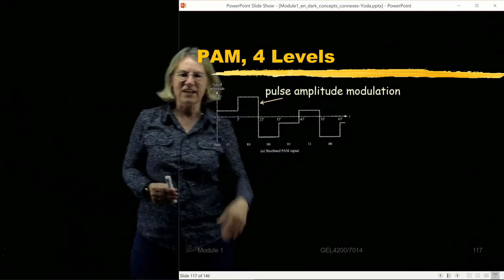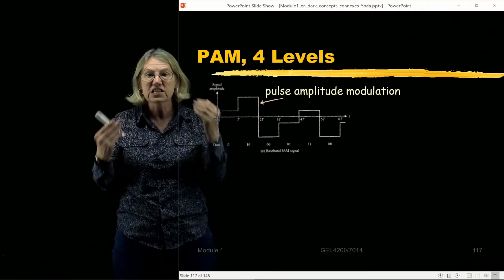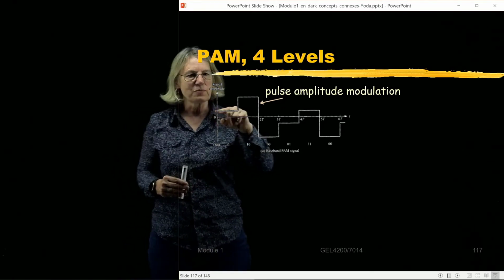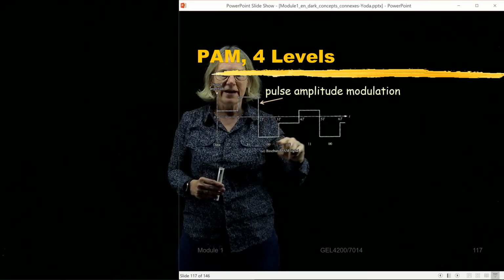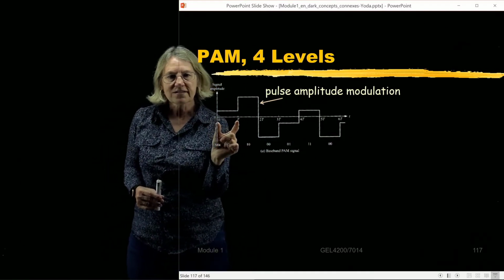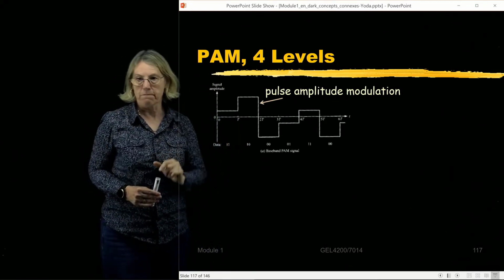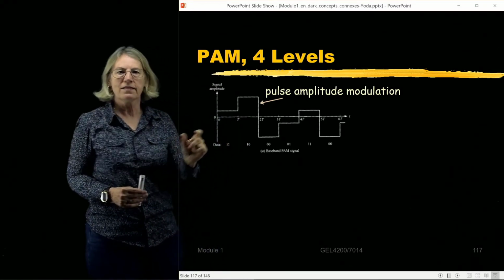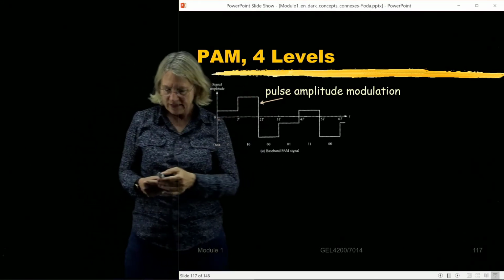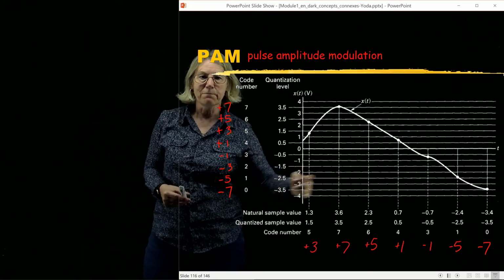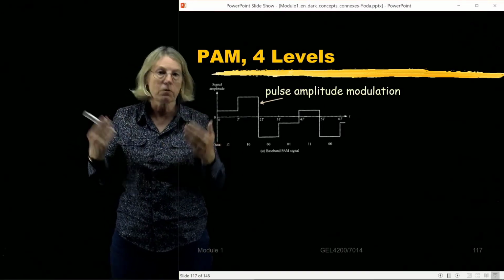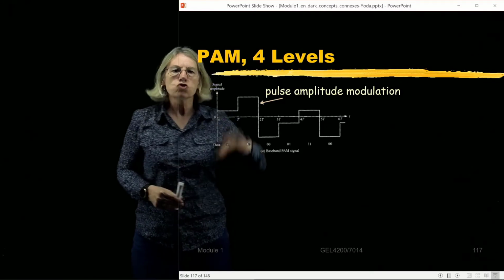So I've given different kinds of names. It's either the amplitude, which is the physical voltage that's being sent. So during this interval, I send voltage level 1, voltage level 3, minus 3, minus 1, etc. This interval of time, I call a symbol time. That's the duration in time that my symbol level lasts. So I say I'm going to send one symbol after the other. We can think of it as representing the time between samples, but in this case, it's actually the time between transmissions. I send a symbol for a certain interval of time.